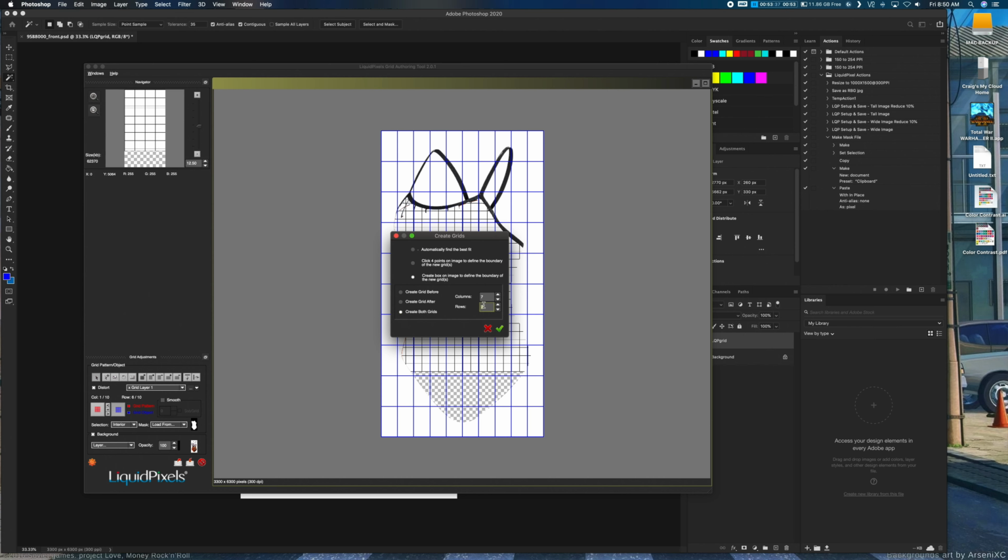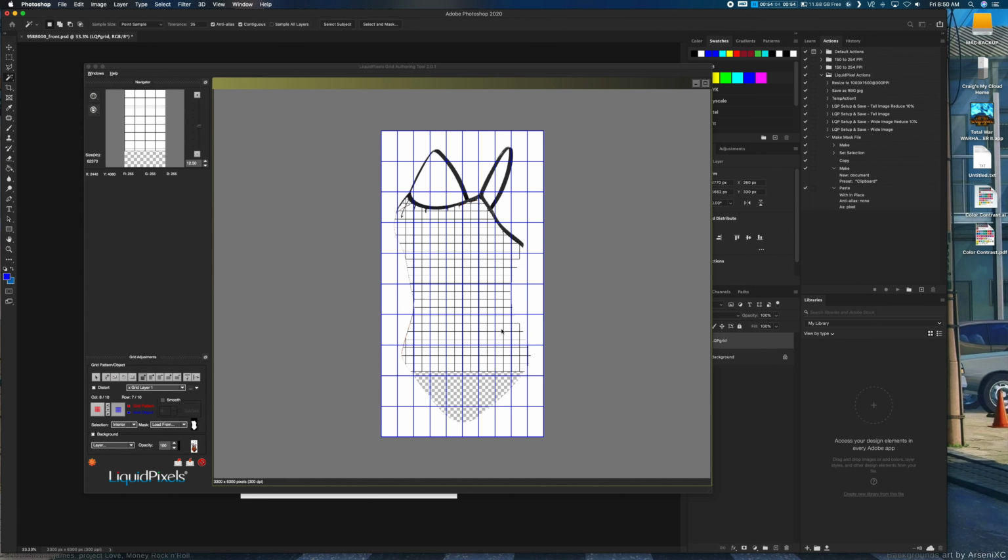We can go here and make it columns and rows, and this basically gives you an idea of how many control points you want to be able to manipulate here. If we're doing something really small and simple, you may only need like a 2x2 box. If you're doing something larger and more complex, you may want a 10x10 or even higher. So I'm just going to go somewhere in the middle here and go 7x7 and click OK.